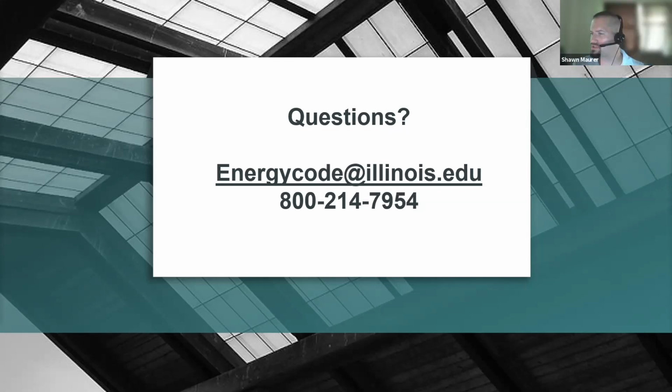We did have a question as well come in about entering pump horsepower information. The Energy Code doesn't have any specific requirements for pump horsepower for hydronic systems. It's usually taken care of by the design of the system. It does have requirements for controls on those pumps though, VFDs and things like that. Those are included in the checklists for the program, depending on what type of hydronic systems you select. It'll input things in the checklist to check off for certain controls on those pumps. But there is no pump horsepower input because it doesn't need to be modeled by the program.